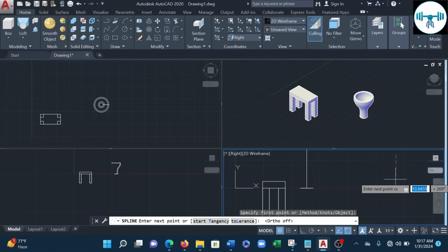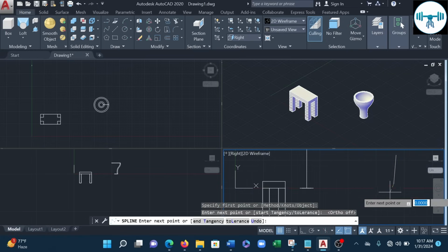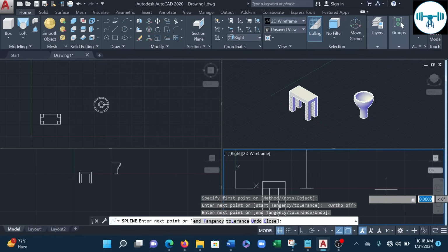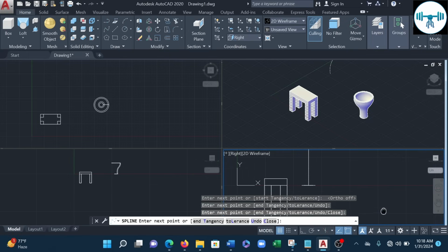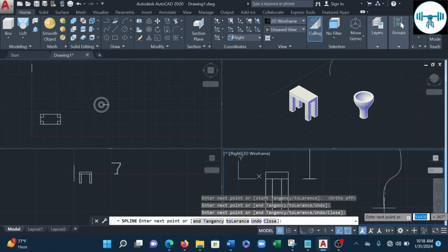Okay, so I'm just going to drop it here. Can you see? Once I release it, I can play around with it. Once I click, I can bend it into any direction I want. That's the beauty of spline. I'm just drawing with freeform, just drawing with my imagination. I'm not drawing with any dimension. I'm just using my imagination to imagine half of the profile of a wine glass.